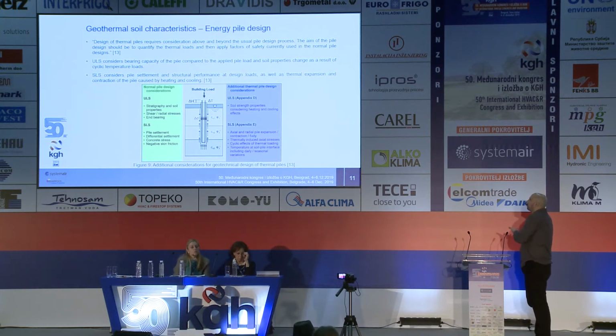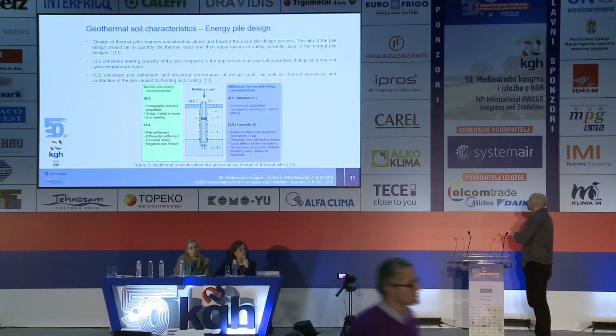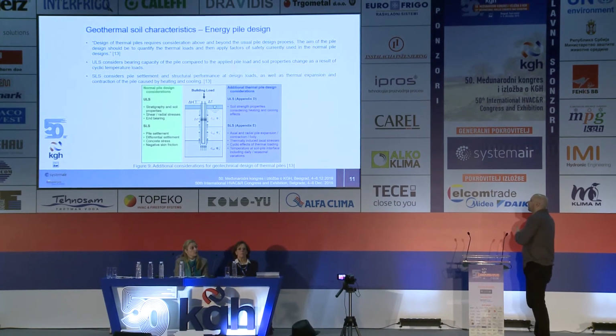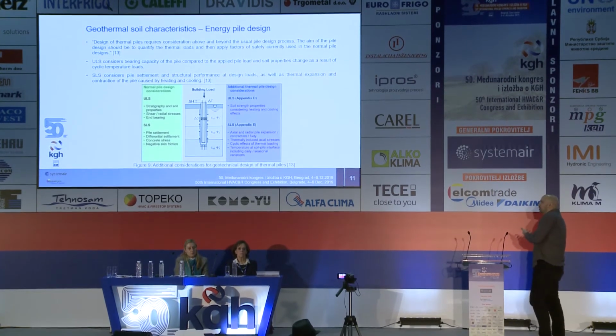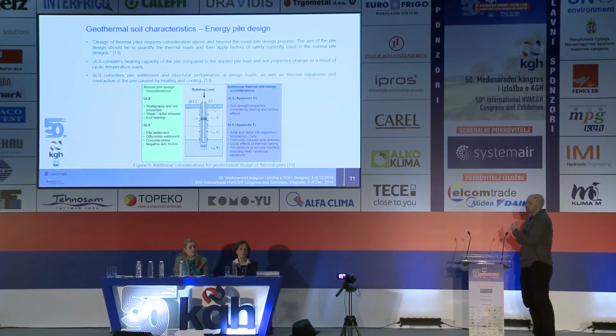Design of thermal piles requires consideration above and beyond the usual pile design process. The aim of the pile design should be to quantify the thermal loads and then apply factors of safety currently used in the normal pile designs. What does that mean? Well, for example, when we design structural elements or structure as a whole, we have two limit states, ultimate limit state and serviceability limit state.